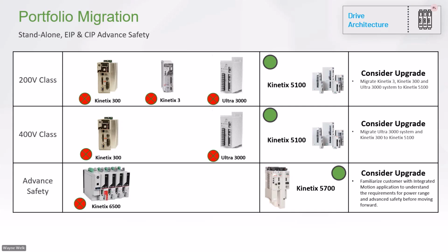It uses either its own KNX 5100 software for programming your indexed motion profiles, or it uses Rockwell's Connected Components Workbench with a Micro 800 controller, or it can interface with a Logix PLC via an AOI. The Kinetix 5100 servo drive platform is available to cover the continuous and peak current performance of the entire range of Ultra 3000 drives. And finally, same as the Kinetix 6200, the Kinetix 6500 with advanced safety functions on SIP motion should be considered for migrations to the Kinetix 5700.